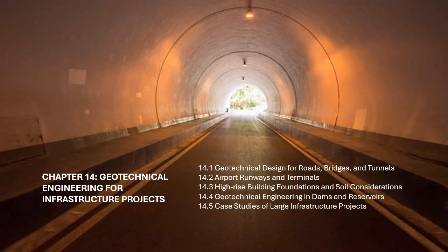Ground movement and settlement. Tunneling operations can lead to ground movement and settlement above and around the tunnel, potentially affecting nearby structures. Geotechnical engineers conduct ground movement analysis to predict and mitigate settlement, displacement, and the risk of surface subsidence. Ground reinforcement techniques, such as soil nails or jet grouting, may be used to stabilize the ground during tunneling.